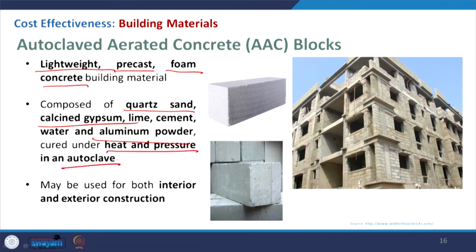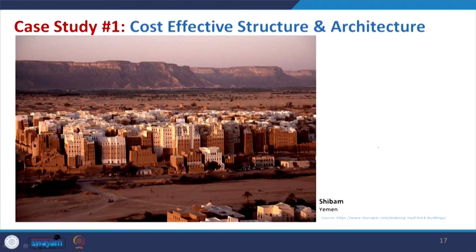That is why the name also comes into the picture. So, that can be used as an external wall, or it may also be used in the internal, and this is useful, as you can see within the RC frame that this block is being used. Because it is light, it is easy for the workmen to handle, and it can be used with few layers so that a full wall can be made.